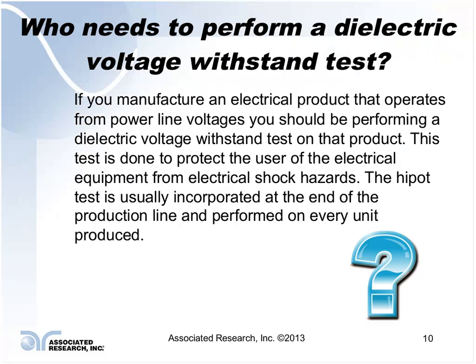Okay. Who actually needs to perform a dielectric voltage withstand test? Well, if you manufacture an electrical product that operates from power line voltages, you should be performing a dielectric voltage withstand test on that product. This test is done to protect the user of the electrical equipment from an electrical shock hazard.